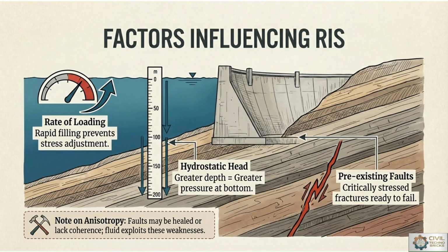What are the factors influencing reservoir induced seismicity? Here: the hydrostatic head, pre-existing faults, rate of loading and anisotropy. These are the four major factors. Rapid reservoir filling increases stress faster than geological materials can adjust. Greater water depth causes higher hydrostatic pressure on underlying rocks.